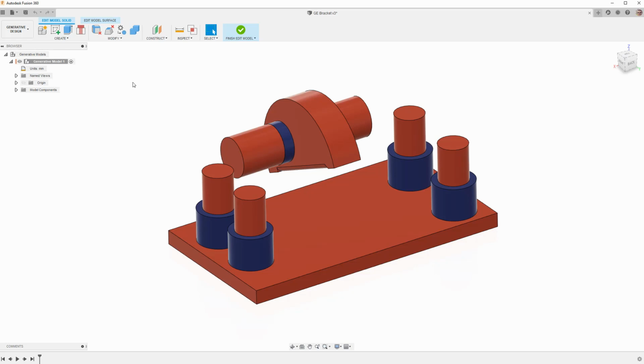And if you do that to the model at the design workspace, those edits are at the top level. Everyone sees them, and a lot of folks don't care about that stuff. They don't need to know that you used a command to automatically find all the small holes and fasteners and components that are under 0.5 millimeter in total size and got rid of them. Right? They don't care about that. So this is a sort of sub design workspace. We call it the edit model workspace, and it is buried one level deep. So it's in the generative design space.